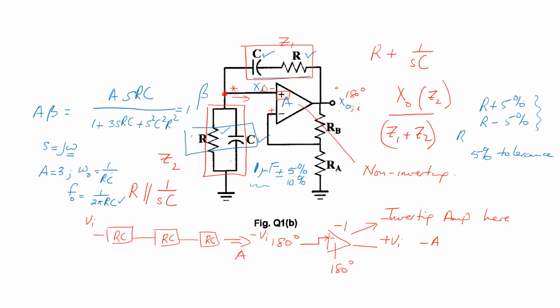When you calculate any resistor and capacitor, you have to assume a value for one of them, like a capacitor at 1 microfarad. What was the reason for assuming it is 1 microfarad? You have to start somewhere, because for the oscillator you need both an R and a C, so you have to make a choice.